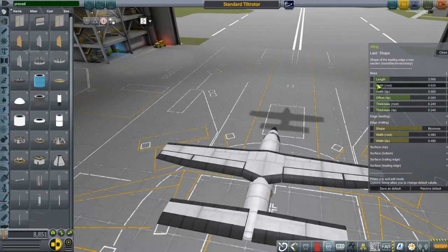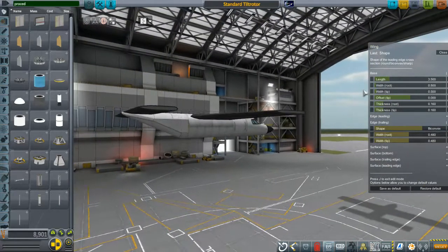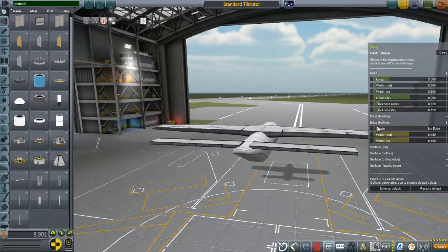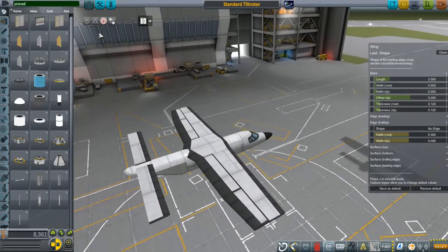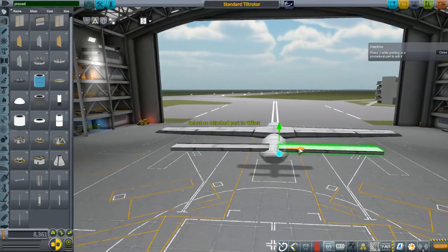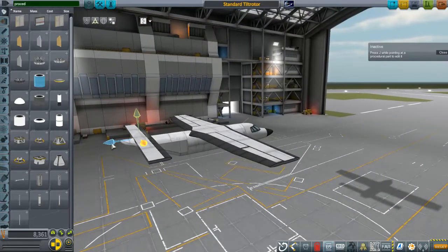We start by cutting down our width to something like half a meter. We cut our thickness in half, so that we have a thinner tail plane. Actually, we're going to cut that in half again, more or less, because we want a thin tail plane. And then the trailing edge goes away because we're adding control surfaces there too. Positioning on this, the reason I've got this a little bit longer is because I'm doing the same overlap trick where they're pretty much just touching right back there, and then dragging the whole assembly straight back.